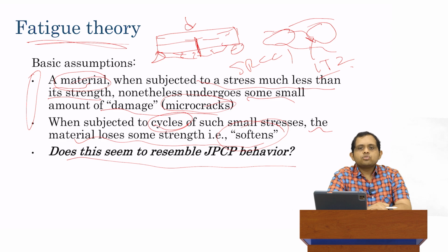As I said, using a variety of techniques, whether visual or audio, several techniques have shown that this indeed is what happens, that in concrete slabs or in concrete beams, application of this small amount of stress does indeed lead to the development of micro cracks. And two, as we shall see, several tests have also shown for concrete beams as well as for concrete slabs